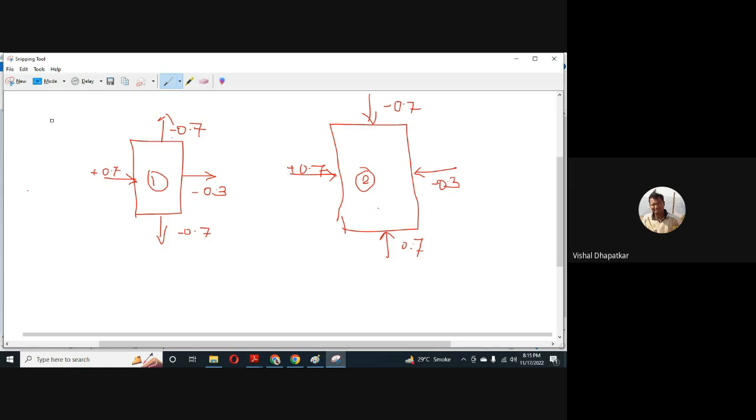Okay. So in the first one we are showing this direction of wind. It is away from the wall, right? So what is it creating? It is creating tension in the wall or suction in the wall. That's why it is given as a coefficient of minus 0.3. So whenever this wind blows in this direction, the wind will go like this and it will create suction over here, right? So this portion will have a pull-out force, like a pulling effect. That's why it is given as minus 0.3.